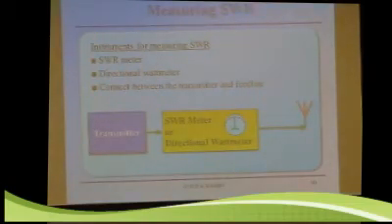Okay, if you want to measure your SWR, how do you do that? Well, there's something called an SWR meter that most people have used. You also can use a directional watt meter. That is where you measure the wattage to the antenna and the wattage being reflected back from the antenna, and that tells you. In either case, you put it between your transmitter and your feed line. So you put it right at the transmitter because you've got a little bit of coax there, but presumably it would be only 3 feet or so, so it's not enough to really affect that much. But then you have almost all your coax, feed line, and antenna after the SWR directional watt meter.